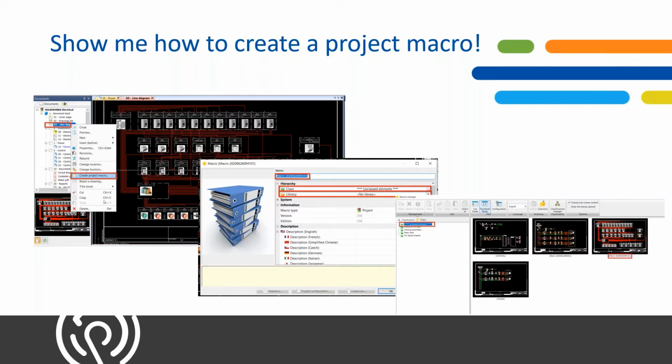Once we create that project macro, we can insert it into a new project, and we could also edit that project macro without editing the original. That allows us to reuse our data, save our time, and also populate new projects with just a few clicks. And the way we do that is we want to select our sheet on the left-hand side in our design window.